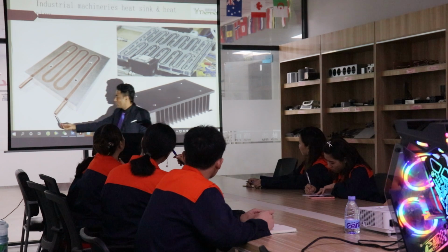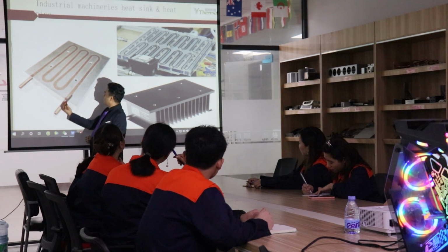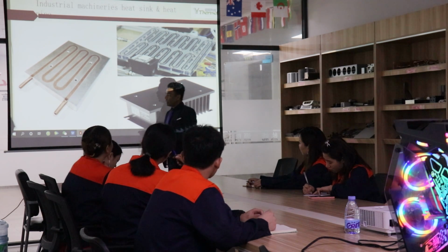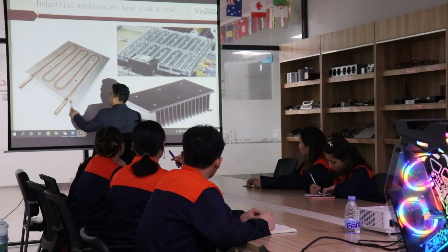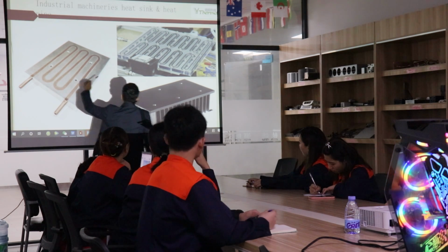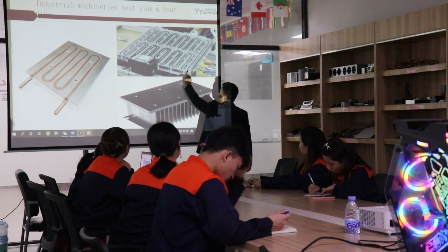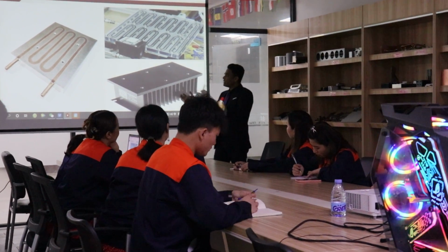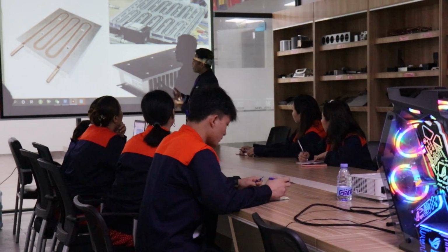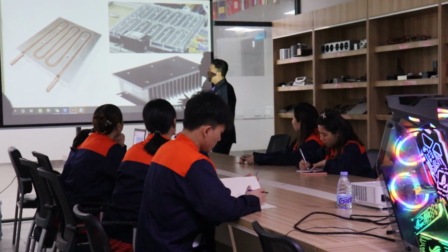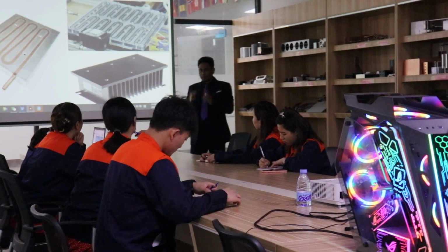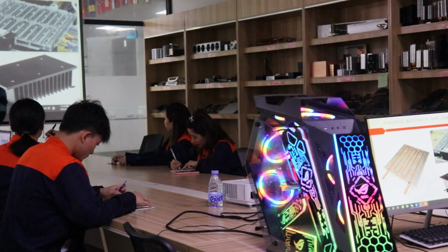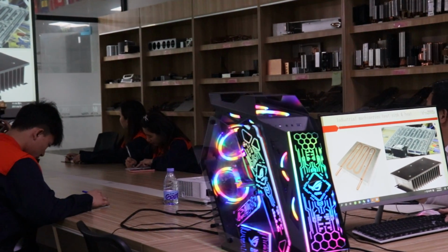We use some working fluid inside. In thermal engineering we call it the working fluid. This fluid is used as cooling control, cooling management, cooling solutions. It also uses a heat sink. Various materials: we use aluminum, copper, also titanium. For most thermal solutions we use heat sink, mostly copper for the pipe, aluminum for the heat sink. And next.